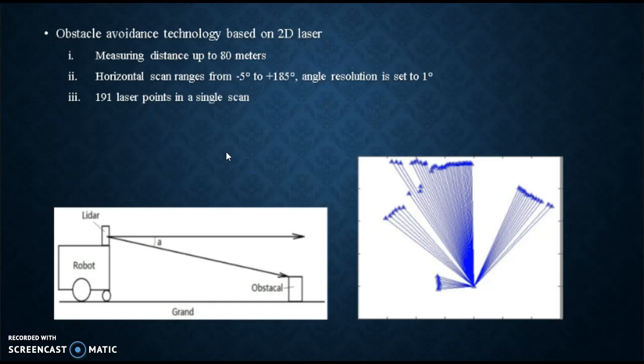The theory of the artificial potential field was proposed by Khatib. He defined the influence of the target on the robot as a virtual attractive force, and the influence of obstacles on the robot as a virtual repulsive force. The direction of the resultant force is also the direction of the next movement of the robot.